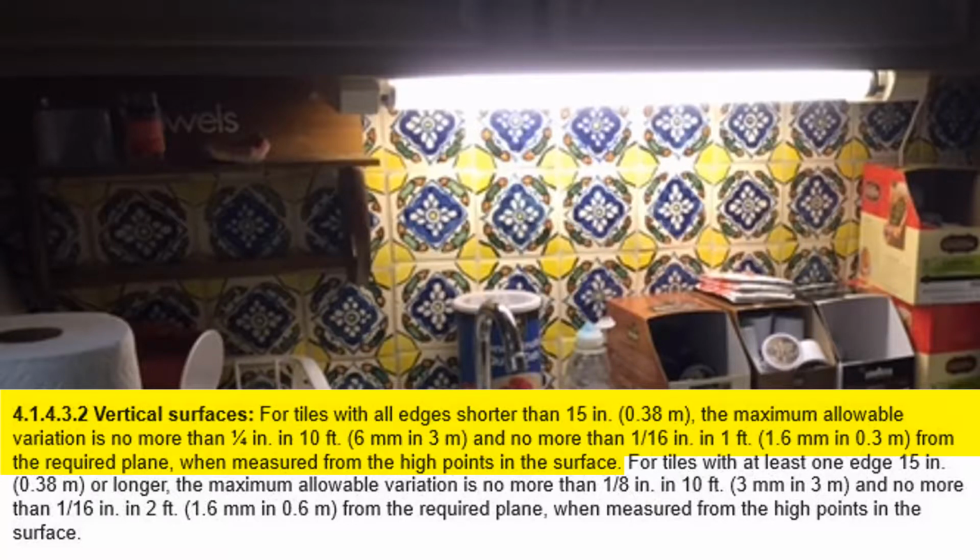4.1.4.3.2. Vertical surfaces. For tiles with all edges shorter than 15 inches, the maximum allowable variation is not more than a 1/4 inch in 10 feet and no more than a 1/16 inch in 1 foot from the required plane when measured from the high points in the surface.